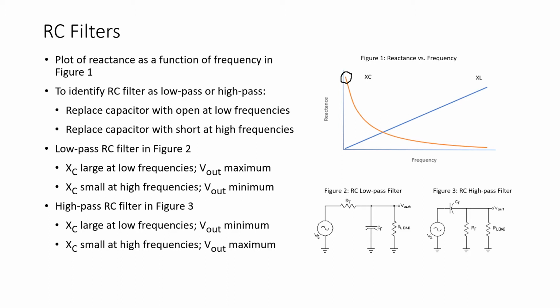So at low frequencies, I can replace the capacitor with an open circuit. And at high frequencies, X sub C is extremely small. It approaches zero. So at high frequencies, I can replace this capacitor with a short.